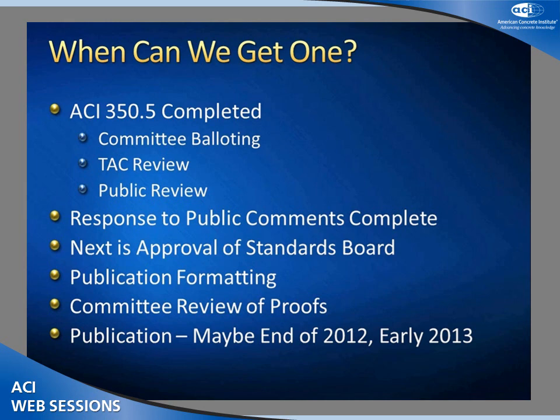Would this specification also be useful for existing structures or liquid containing structures for spill prevention? For spill prevention for oil containing equipment? Sure. Liquid containing structures, the design. There are instances when you have a building that might be exposed. Let's say you have a building that's going to be at a dry dock. It might be partially flooded periodically. You really don't need it most of the time, but sometimes you do. You want an extra level of durability and protection of your reinforcement against corrosion. In your structure, you can use the provisions of ACI 350. There's nothing to prevent you from doing that.